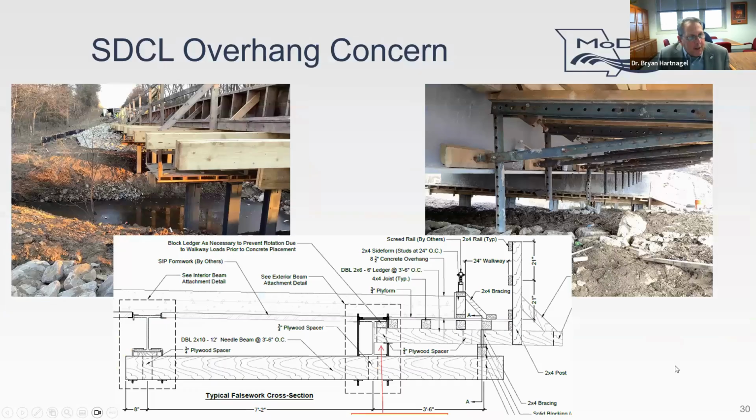When you have girders that shallow, you do have an overhang concern or twisting of the exterior girder when you use these typical cantilever form brackets. So you've got to understand the stresses that this puts into the girder. Obviously, this puts a lot of torsion unless you brace these very well.